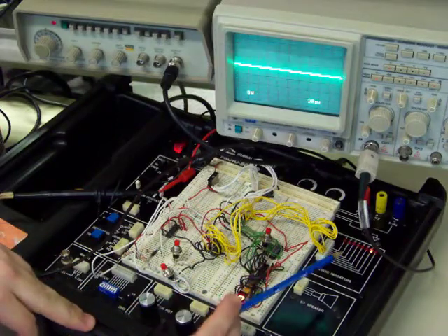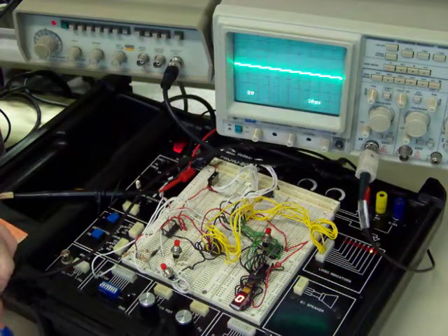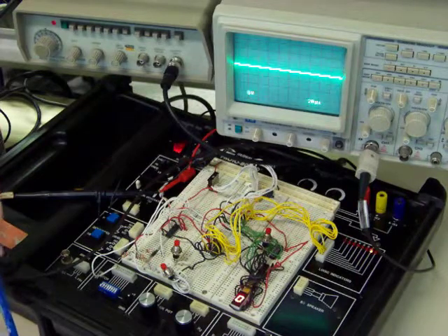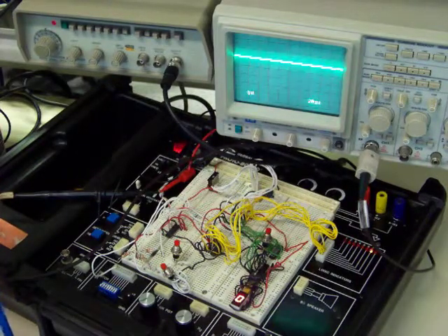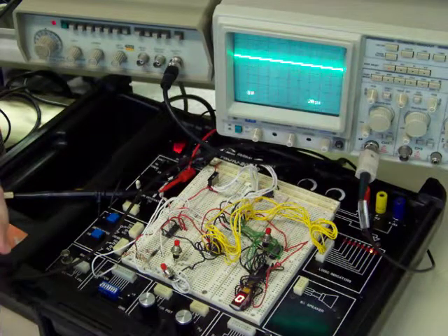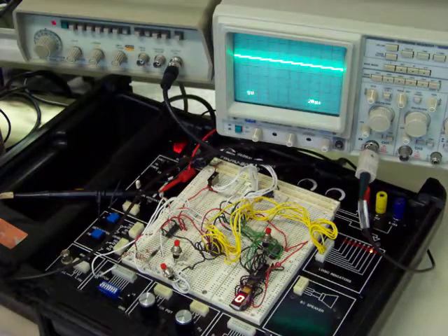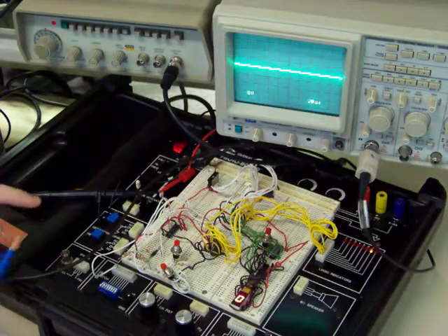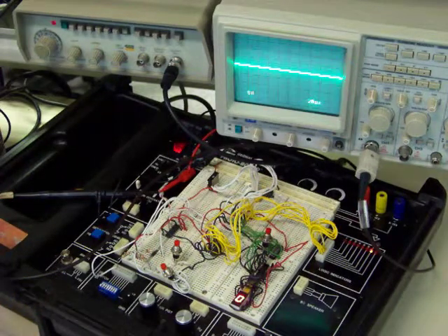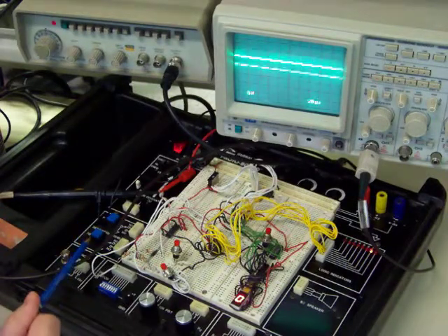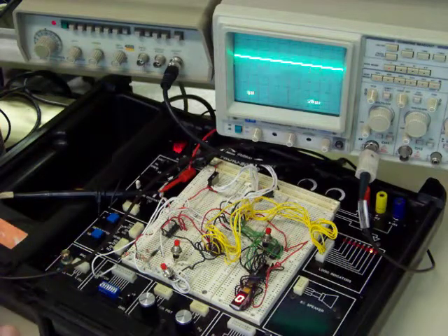As you can take note, it bounces around to a random address. It says in the lab that we could halt that by putting a debounce circuit into the middle of it. However, we're not making that on a menu to choose it, we're just manually entering that in. So in this lab we don't actually do that, but we could, and we could use one of the push buttons here which has a debounce circuit in it.